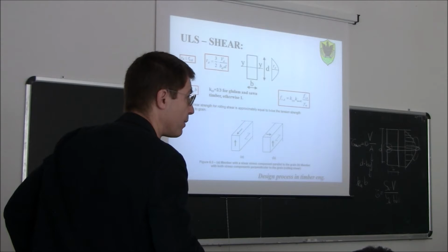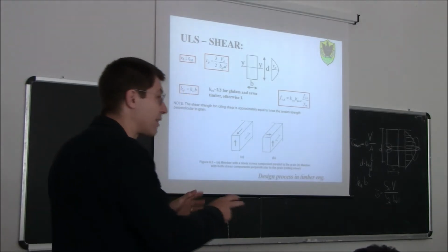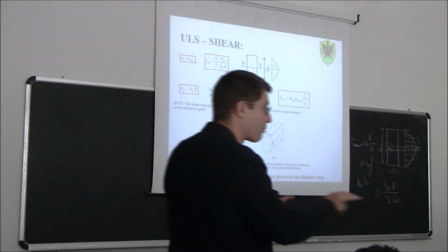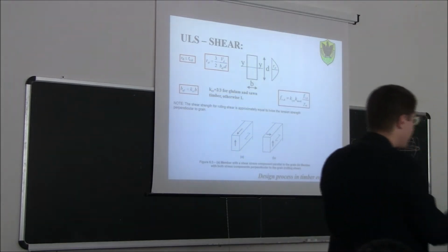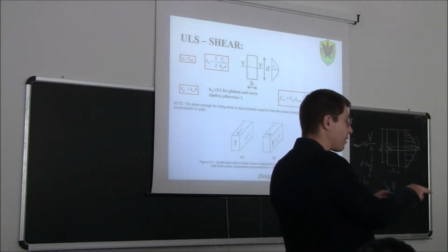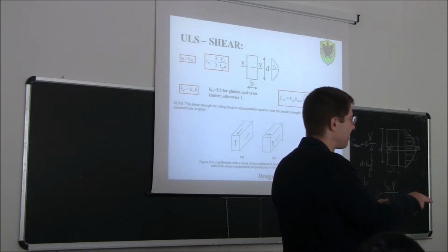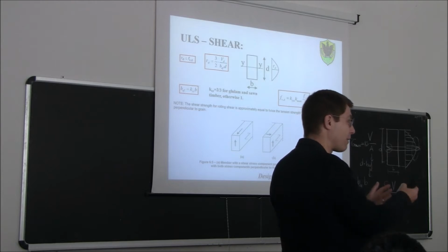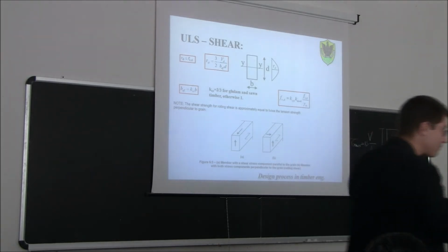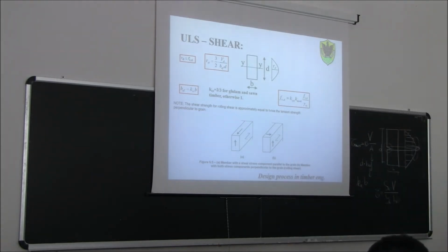Which one would be radial tangential? Here, radial and tangential are directions, but we're talking about planes now. Any plane perpendicular to the grain: well, perpendicular to the grain is only one plane. We just said that perpendicular to the grain is the maximum shear strength.